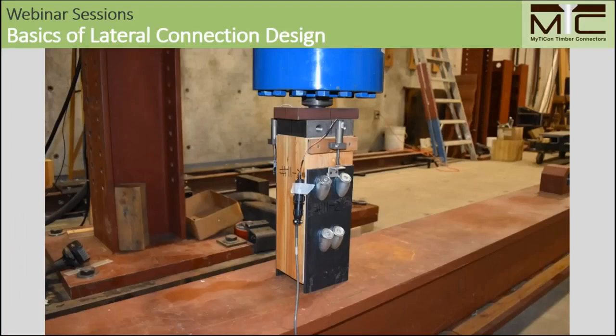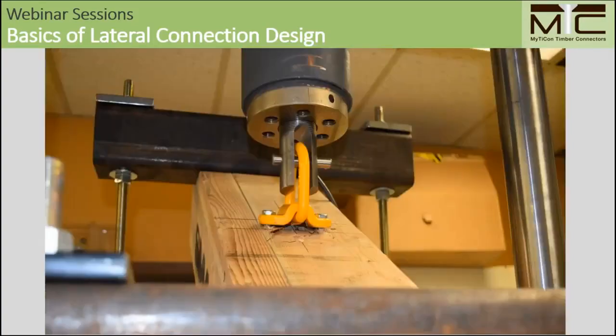And here at Mightycon, we try to give the designer values that you can really rely on. So we do a lot of testing here with local North American universities, also with North American lumber species, because we also have differences here. On this picture, you can see an inclined screw test that will be included with the ICC revisions, but we also do testing for shear, or here a lifting test for our lifting devices, so that we can really say our design values have the right amount of safety factors inherent, and we are confident with providing those tables.